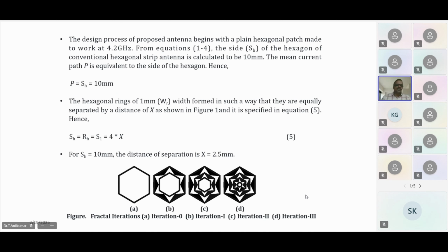So like this, see the composition of the antenna. First, I have taken one hexagonal ring, and the second hexagonal ring is connected to the first hexagonal ring through triangular patches across all the edges. And the fractal in nature is iteration one, iteration two, and iteration three. You can observe the composition, right? So whenever these triangular elements are added, you can bring down multiple resonances in order to form a wide bandwidth. You can observe that in the return loss curve, right? Next.